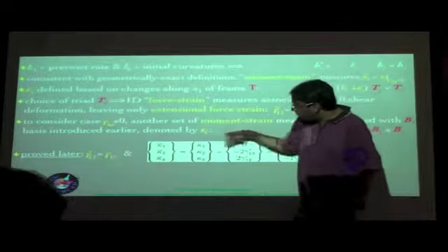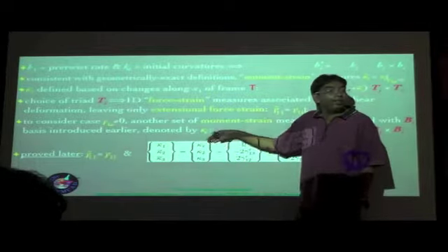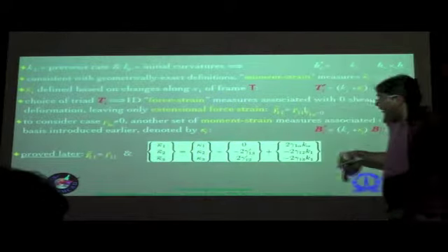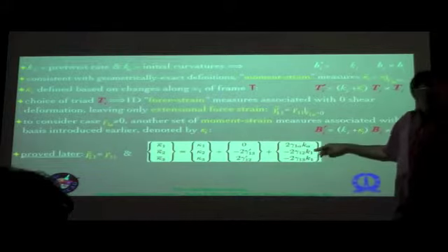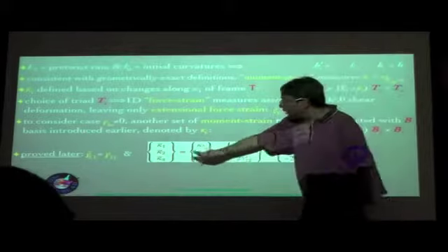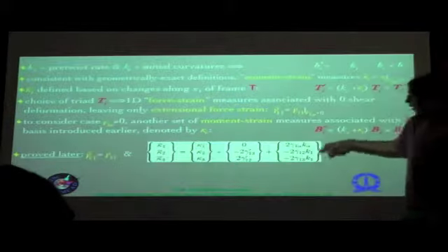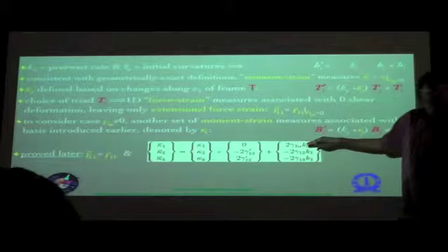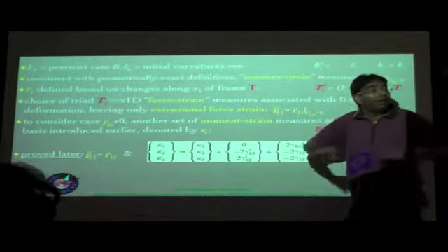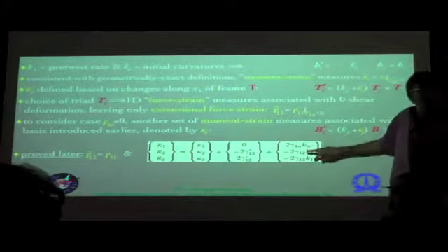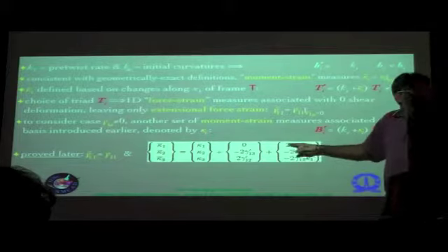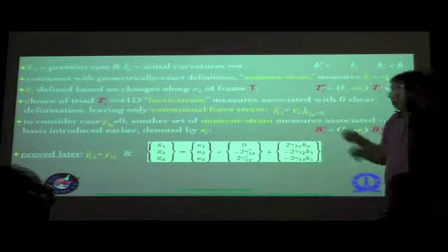So this is all that is there if you have an initial prismatic beam, so that is basically no initial twists and curvature. Once you bring in the initial twists and curvatures, there is a further difference. The initial twist causes a difference in the bending curvatures, and on the other hand the initial curvatures cause a difference in the twist per unit length. So basically the roles are reversed, but again it is driven by the transverse shear strains.